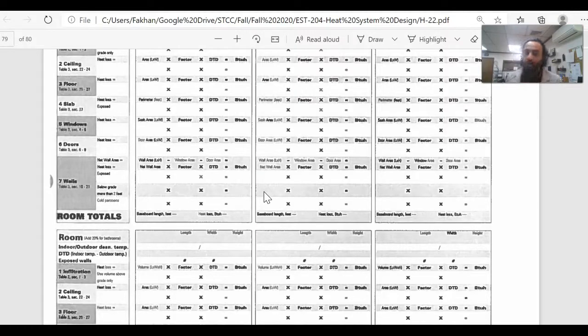Before I go, what do you think the difference is going to be if you're going to design for cooling? That's going to be a little bit different, right? Basically, you can use the same exact material because the material is going to be the same, but for cooling, we'll change the temperature difference, because cooling is going to be between hot outside and cold inside, and heat will move actually from the outside to the inside. So it's going to be a reverse.